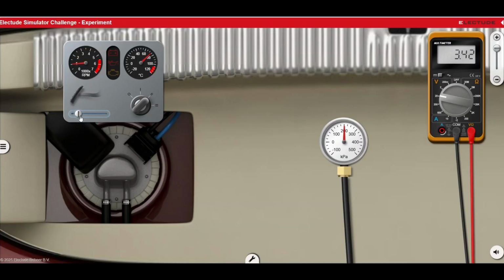And also, when you have a good pump, whenever you raise the RPMs, the pressure doesn't fall. If you have the fuel gauge on, the engine is running at idle, and you increase the RPM and the pressure falls, that means you have a weak pump or some restriction in the piping.